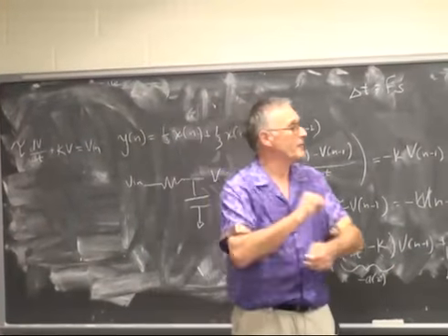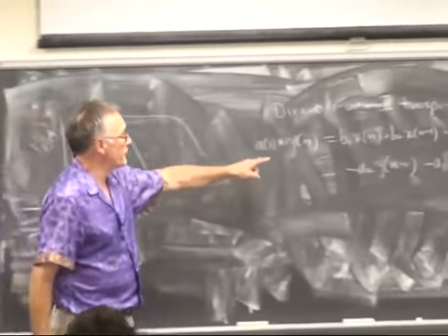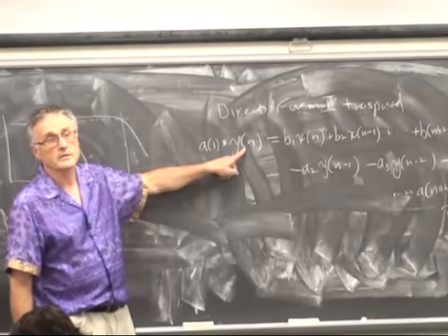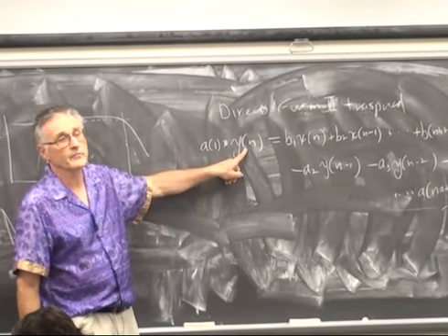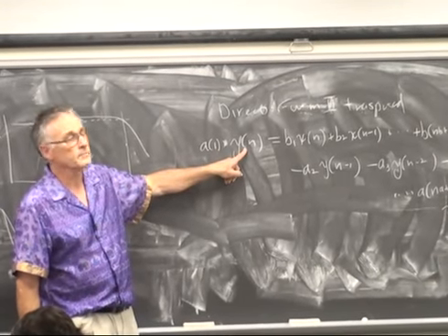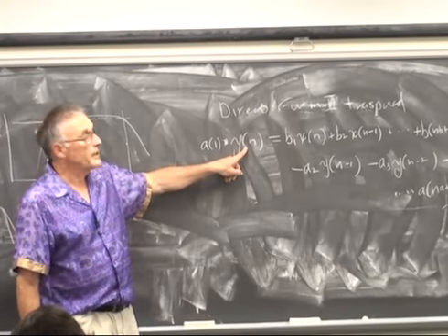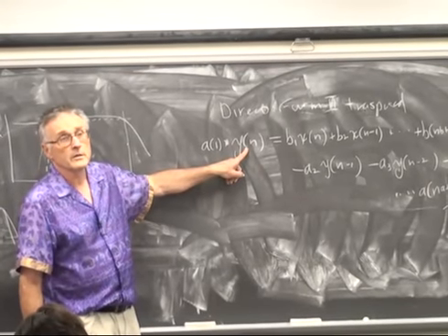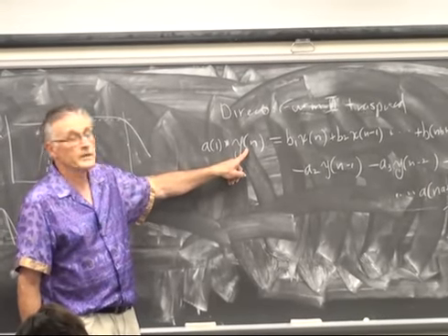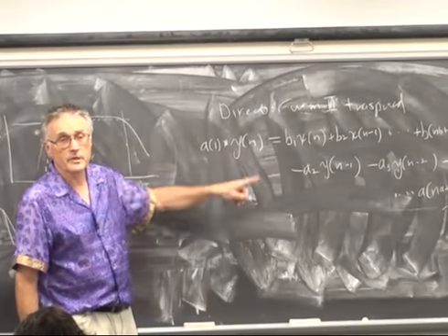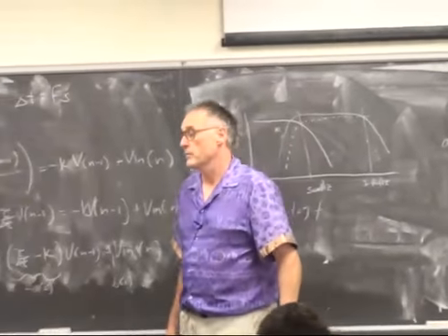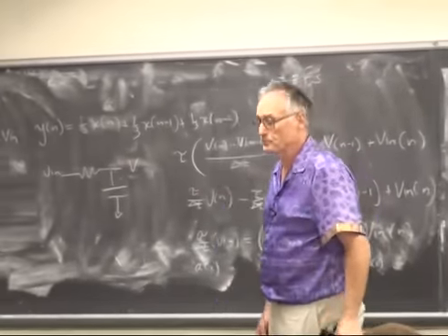In other words, you have to calculate a new sample output every 22 microseconds. That's not hard on the FPGA. That's easy. You have to calculate a new sample every 22 microseconds for each channel, and I'm going to ask you to do the two filter operations for the two channels separately.